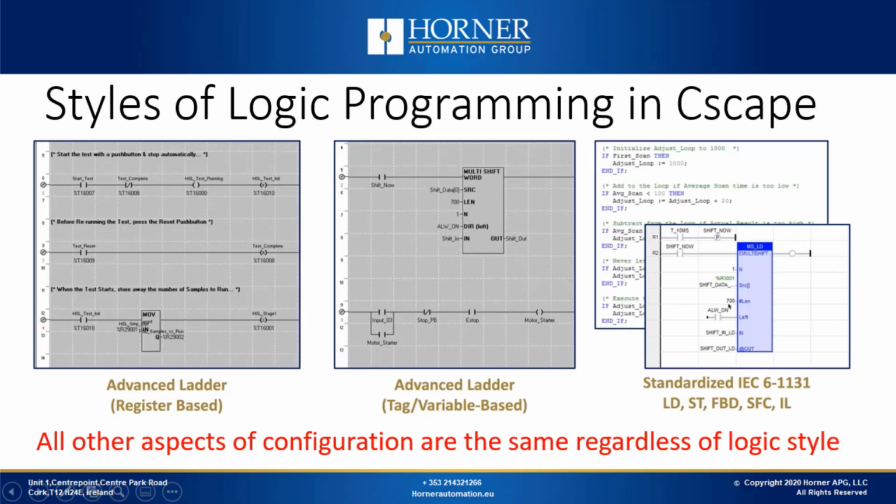First, let's take a look at the different logic styles side by side. In Cscape, there is only one way to configure things, such as screen graphics, communications configuration, and hardware configuration. But we give our users a choice when it comes to their logic style. There are three languages built into Cscape that determine the logic style in which users create their programs. The first language created was Register-Based Advanced Ladder.